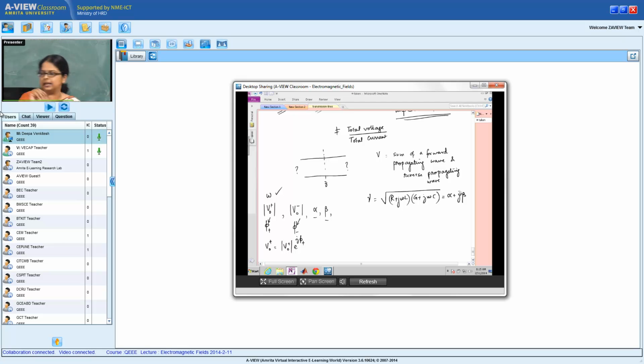So if I have picked a line, if I have decided that my transmission line is a coaxial cable of a certain length, I have already defined my wire, I have already defined my line. For example, if this is my transmission line, I know what the conductor is, what the resistance of the conductor is, how much the capacitance is between the live wire and the ground wire. I know all the details of this wire. So I can actually measure R, inductance, conductance, capacitance. All it needs is a multimeter which can measure all this, right.